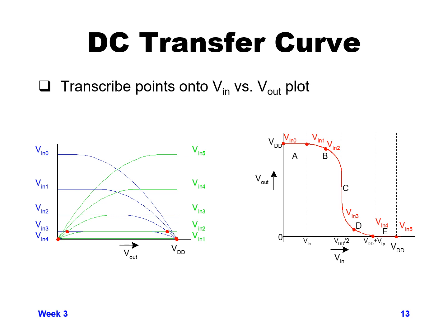So when Vn hits exactly halfway between VDD and ground, we'll get something around Vout halfway between VDD and ground as well. And that will happen if the PMOS and NMOS are exactly balanced with each other in terms of drive strength.